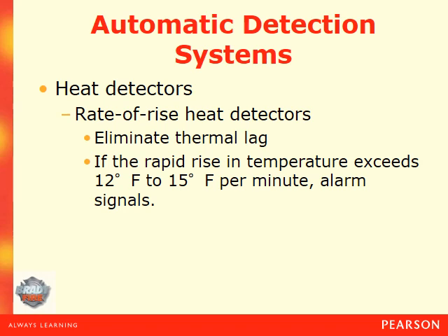Rate-of-rise heat detectors will eliminate the thermal lag. If the rapid rise in the temperature exceeds 12 to 15 degrees per minute, the alarm will signal.